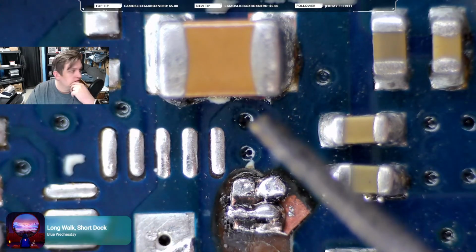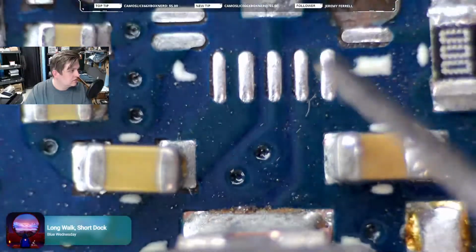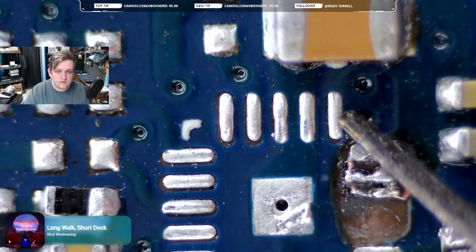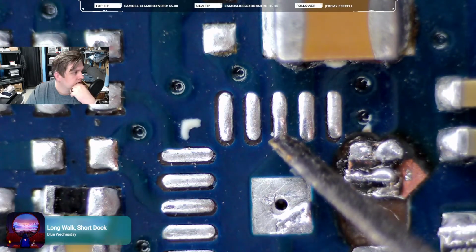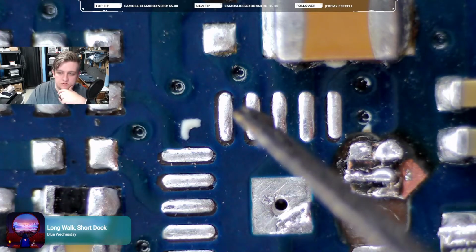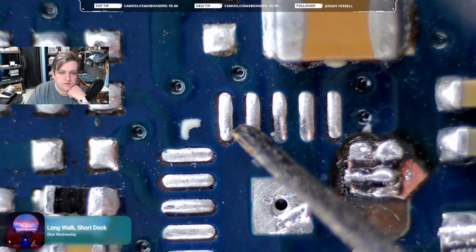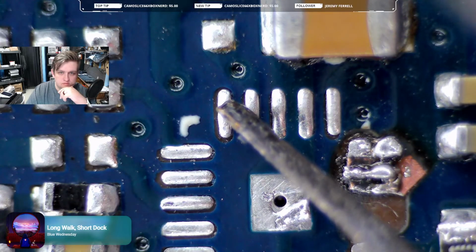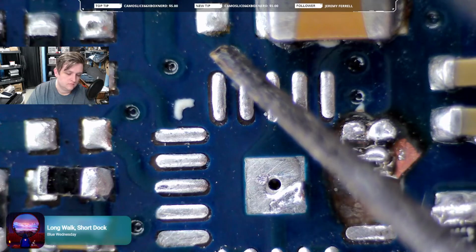Let's see. Because pin 6 goes to the inductor coil that's down here, along with 19 and 20 connecting here. And then 7 is a ground pin, 8 is a ground pin. So 7 and 8 are ground pins. 9 is the power good indicator, an open drain output when the output voltage is within 90 to 120% of the regulation point. So this one checks if the power is good. And then this one is number 10, not connected. That goes to a via. Interesting.